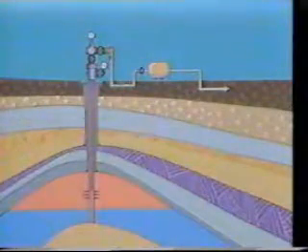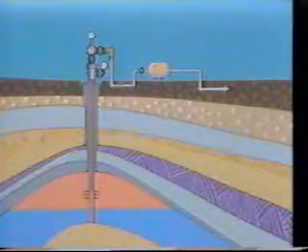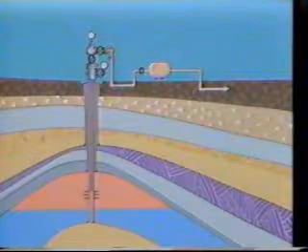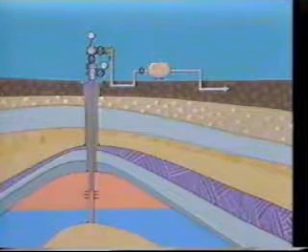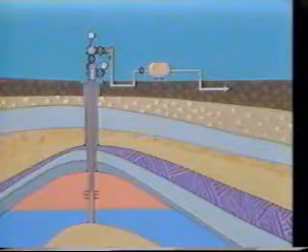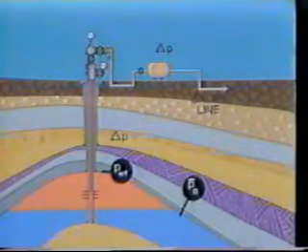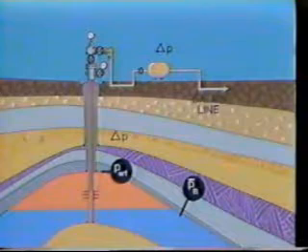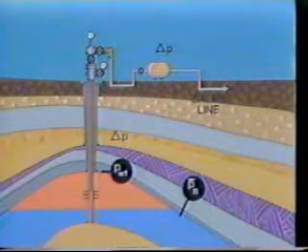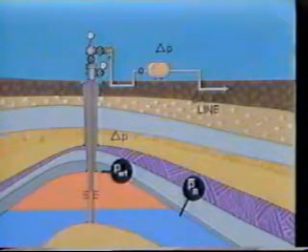A gas well will no longer flow when the average reservoir pressure drops to a value equal to the pressure in the well bore imposed by the back pressure. The well bore back pressure, P sub WF, as we see here, is the sum of the back pressure imposed by the sales line at the surface, plus the pressure loss that occurs in the gathering system and the tubing.